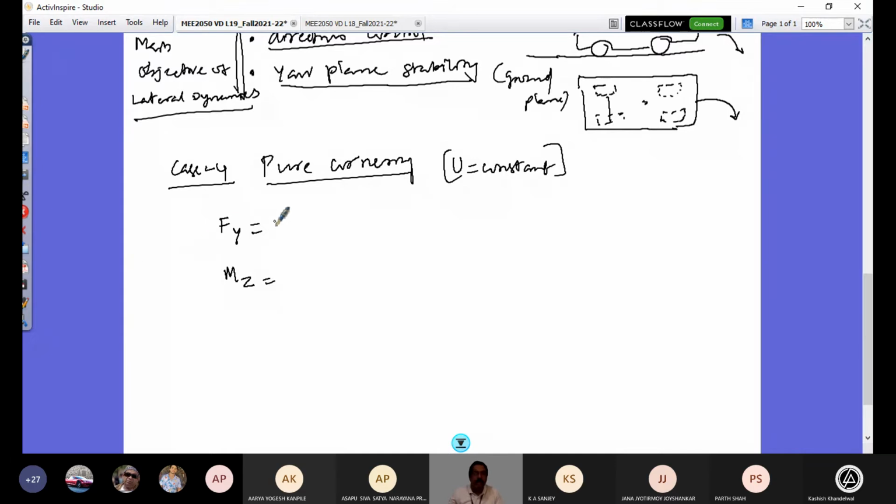So I would have only these two equations. It's going to be M into V dot plus RU, right? Or you can also write this from the vehicle dynamics point of view: Fy is M into V dot plus RU, small letter. Don't get worried. So Mz is Iz into R dot. That's going to be the same. M is that. There's no notation change of PQR.